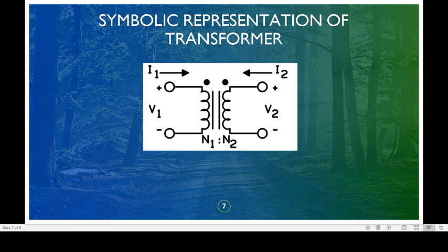Now there is resistance in the windings, and therefore copper loss I square R is present in the winding. Talking about efficiency, the transformer core is made of, for example, silicon, so it would have alternating flux linkage, and therefore it would have iron loss in it, that is eddy current loss. This loss is generally very small, so the efficiency is very high. Also, a transformer is regarded as a static machine, so it does not have any rotating part, and therefore it avoids frictional losses.